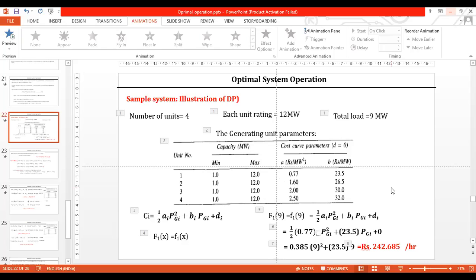Understood. And it is not economical to operate all the units at all times. So I have taken Raichur Thermal Power Station, where totally 8 units are there, out of which 7 units are of 220 megawatt and 1 unit is of 250 megawatt. So now we have to see how to operate these units. It is not economical to operate all these 8 units at all times. So for a given load, for a given constraint, which units to be operated? This is what is known as your unit commitment problem.